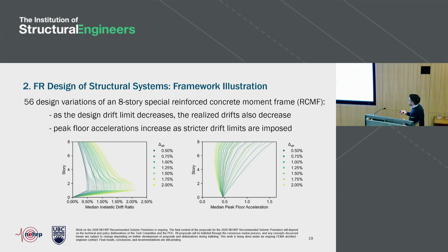And what you can see here is the realized drift of these different designs. And as you'd expect, the tighter the drift limit, the lower the realized drift. And by contrast, the tighter the drift limit, the stiffer the structure, the higher the accelerations that you're going to experience. And this doesn't matter so much when we're talking about the structure, but because we're talking about functional recovery, non-structural components are very important. And that's why we need to circle back later and make sure that we're accounting for the large accelerations associated with potentially very, very stiff structures.